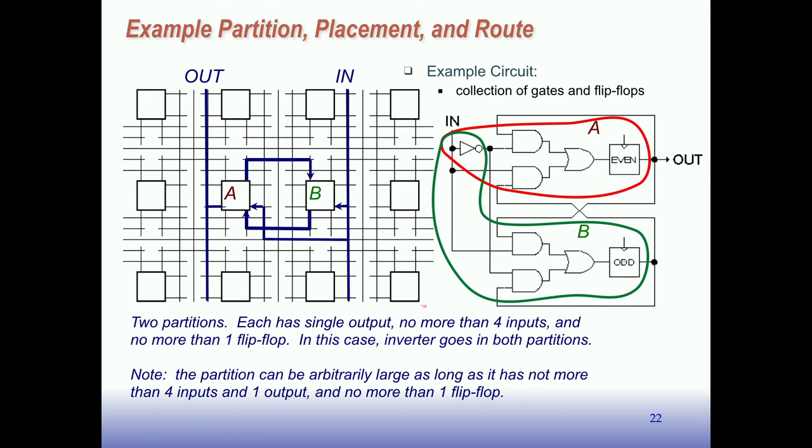Even though designing with FPGAs is faster than ASICs, the tools can take hours to do their job because it's hard to figure out how to place all the cells to get the minimal delay, right? This is the multidimensionality problem. There's lots of connections, and figuring out which pieces need to go close to which other pieces in order to minimize the delay is a hard job. So it tries lots of combinations, and it can run for hours, sometimes overnight.